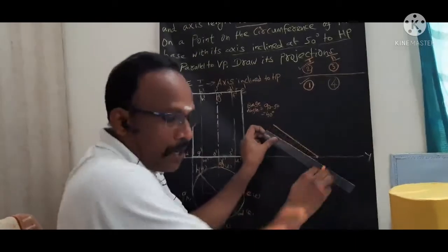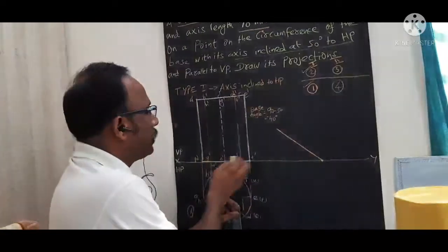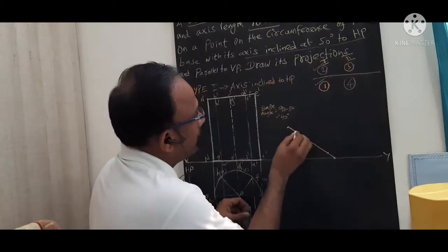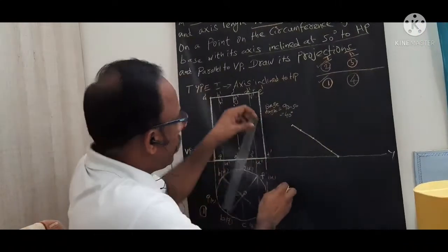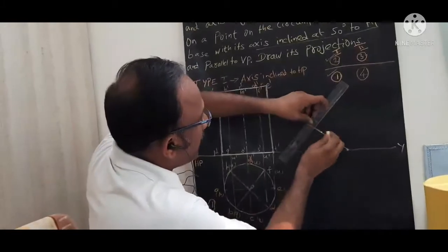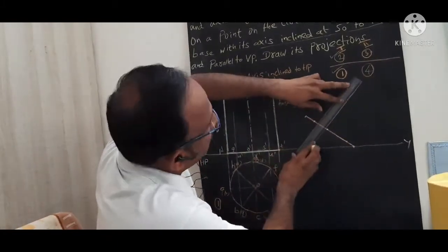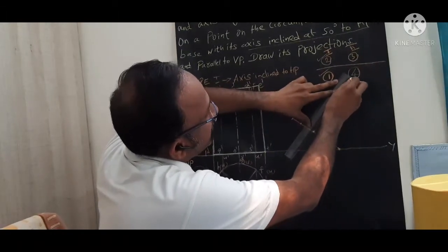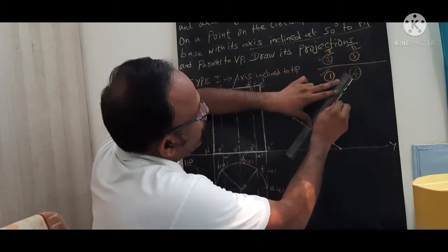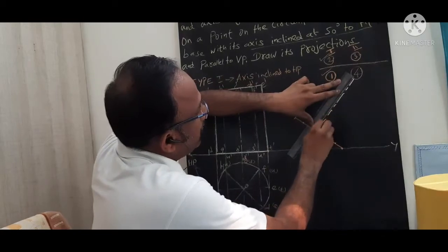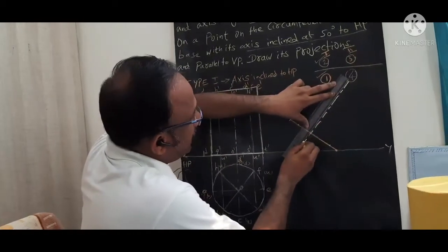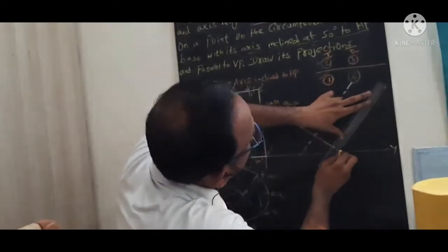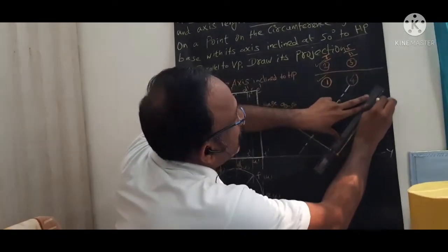Now you need to mark the corresponding points. Whatever points we marked on the bottom edges, you need to mark all these points, right? And in the center point, you need to draw this axis line for 70 mm. For 70 mm, you need to draw this axis line this way. You need to draw again. Then you need to extend this up to this XY reference. Now you need to draw and complete your front view.